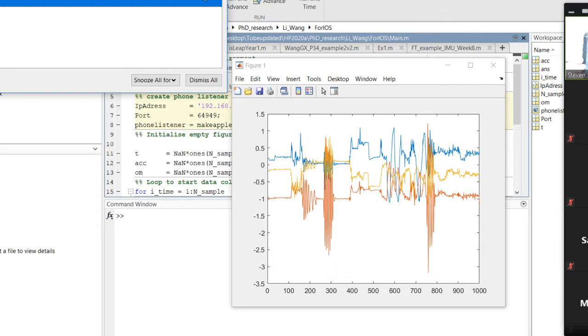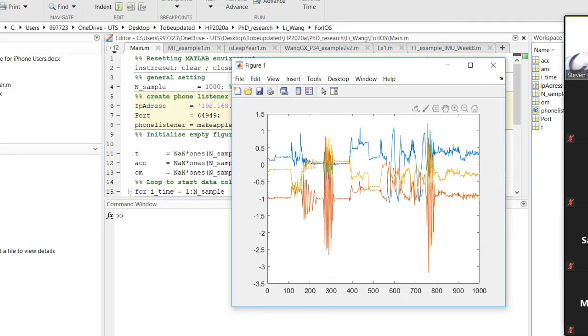But that one is not very accurate. Why? Because the angle and the acceleration have a nonlinear relationship. So some engineers thought of another way, called force feedback. They do not let the pendulum move. They just put in a sensor that can sense how big a force we need to keep it in the original direction. This is another very popular kind, called a force feedback accelerometer. Before, they used very big mechanical systems, so the accelerometer was normally quite big. They put them in missiles and airplanes, mainly for military use, and they could build very highly accurate accelerometers.